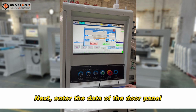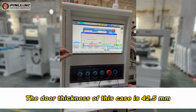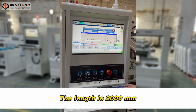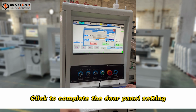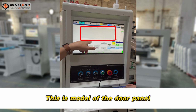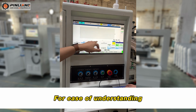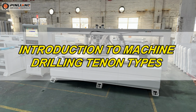Next, enter the data of the door panel. Measure the corresponding data and enter it. The door thickness of this case is 42.5 mm. The length is 2000 mm. The width is 800 mm. Click to complete the door panel setting. This is the model of the door panel. For ease of understanding, this position is called the dot.